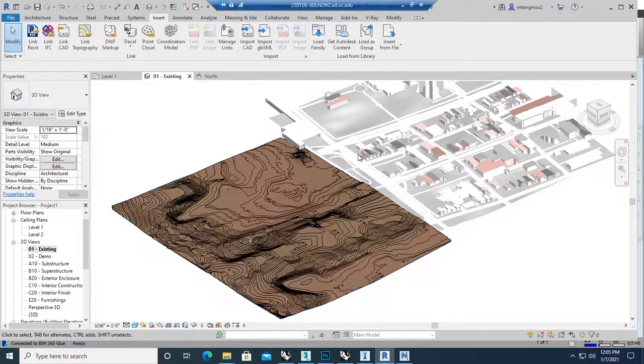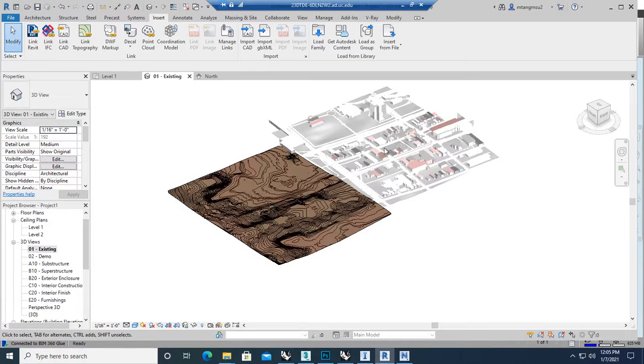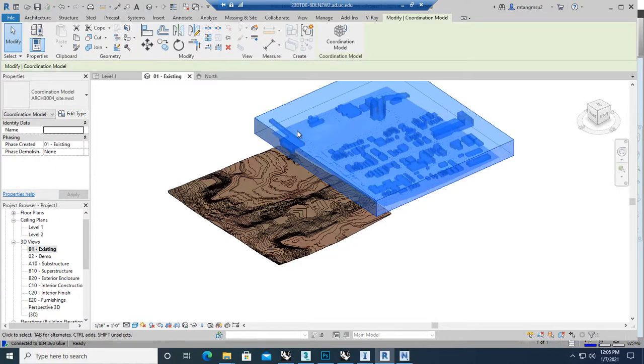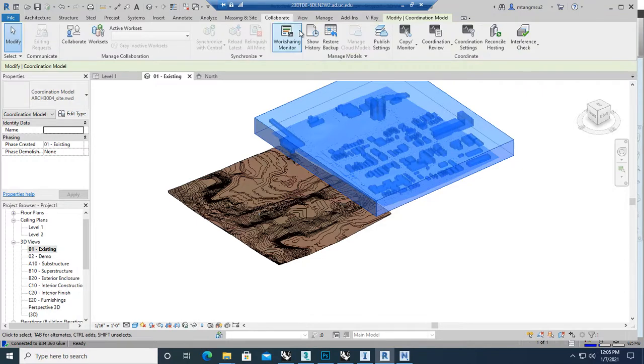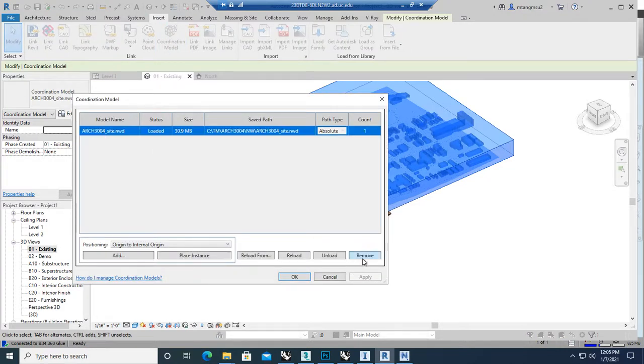You might be wondering why we do this through Navisworks, because by default the Revit model coordination is not really able to communicate with Infraworks. So you have to go through Navisworks to allow this bridge to be established. Right? So here in the Insert, you can always go here. If you don't need this anymore, you can remove it. In fact, I think the Revit file I gave you for the older version does not have this link, so you can actually not worry about this.